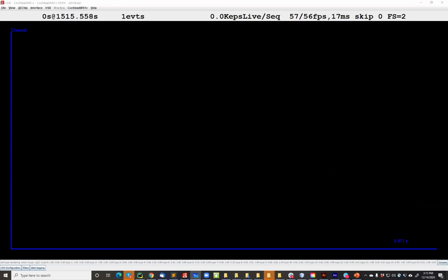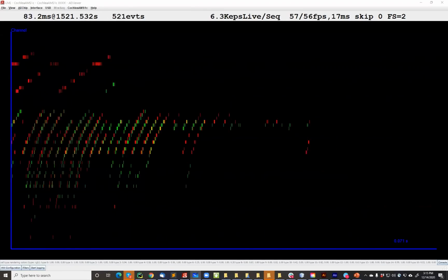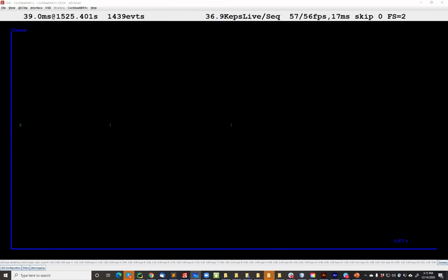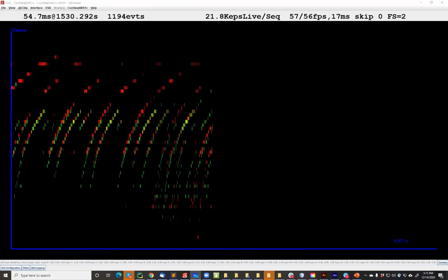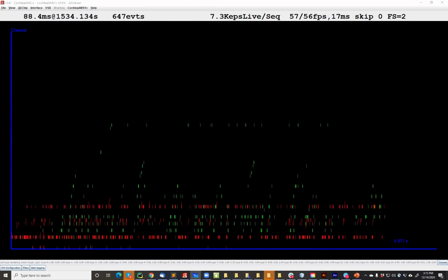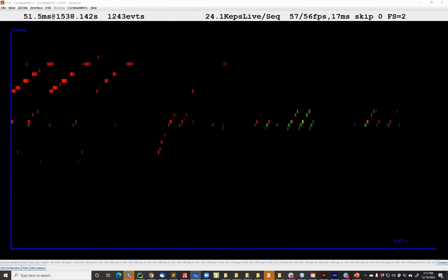In the biological cochlea, it's a very sharp roll-off. I think it's over 200 dB per decade roll-off. So there's no way we're ever going to build this, right? And so Dick Lyon and Carver Mead, who built the first electronic model, made a cascaded filter bank. The output of the first filter feeds into the second filter, the output of the second filter feeds into the third filter.